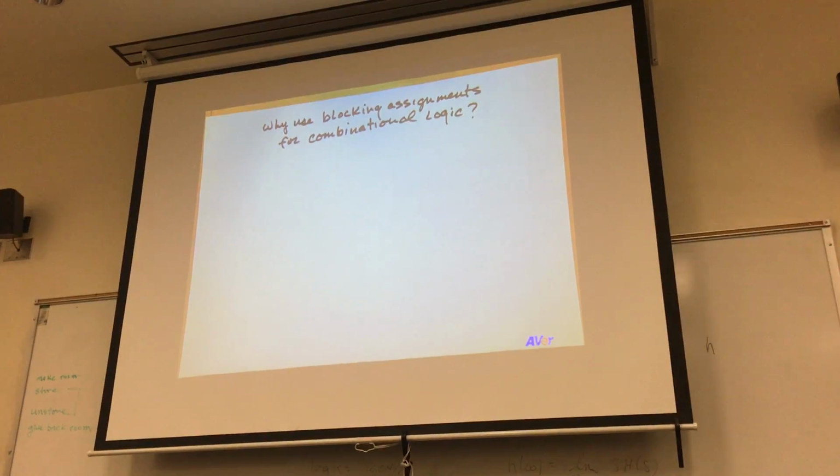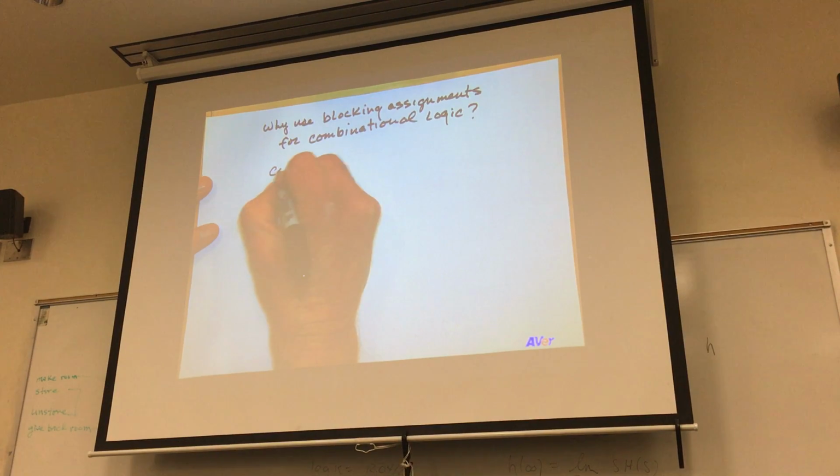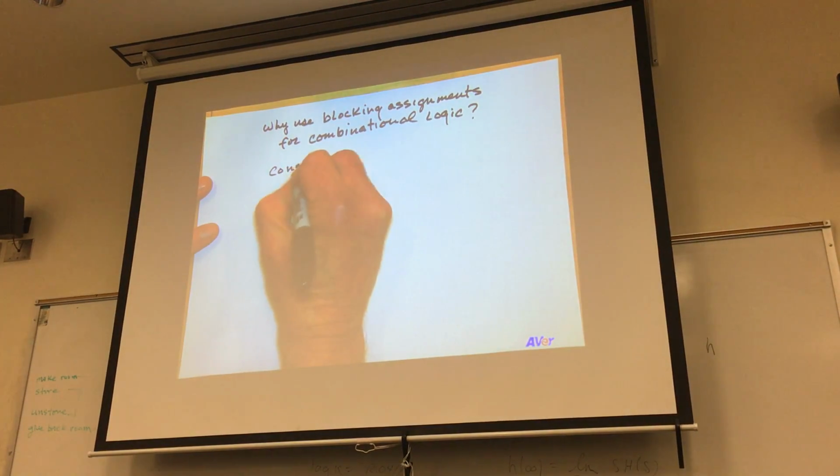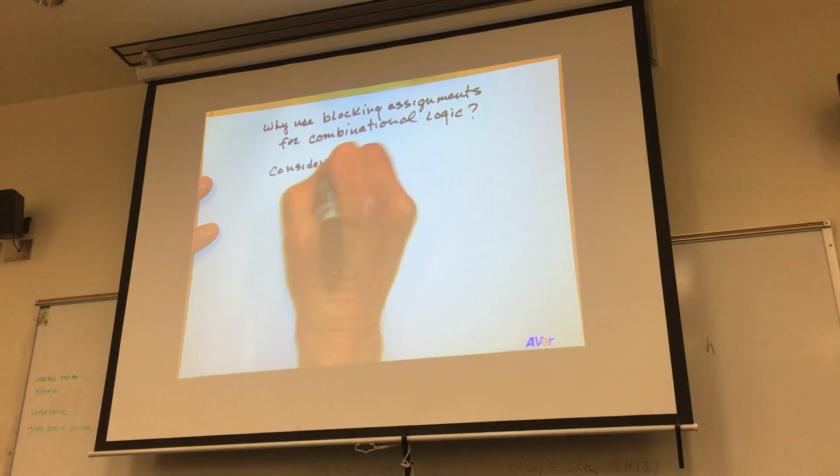Blocking assignments are for combinational logic and non-blocking are for sequential logic. And I want to give you some examples to illustrate why that is so highly recommended. So I want to look at a simple program here.